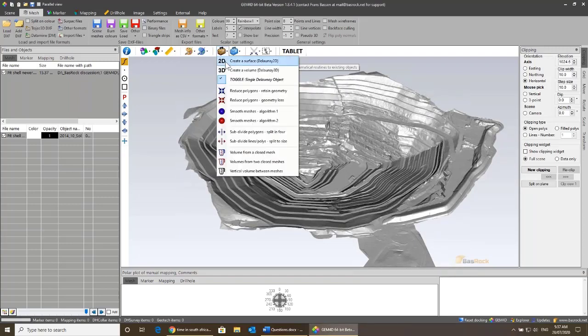The one that I'll be using is this surface Delaunay 2D. So Delaunay, I'm not saying the name to confuse people. I'm just saying the name to say that's the algorithm I'm using to create a surface onto something else. So create a Delaunay surface. I want to create a Delaunay surface, but when I do the Delaunays, that's the 2D and the 3D Delaunays, I'll cover both just to show you the differences. You'll see there's also a toggle button involved, and that toggle button is really important.